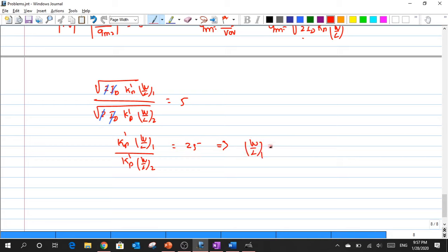Now we will try to solve the second question. We need to find the range of input voltage over which the MOS transistors are operated in the saturation regime. We know from the definition, so I'll be using this figure to ensure that you understand what has been asked. First of all, I need to define the base value of this V out. The base value is nothing but the Q point, and we know this Q point is supposed to be equal to VDD minus this VGS2.